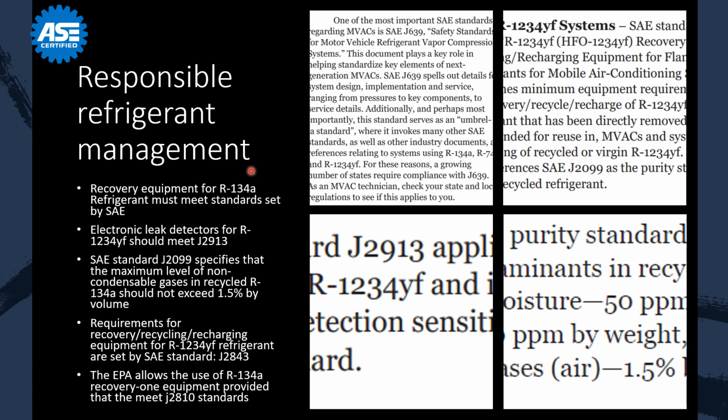R134A, the equipment for R134A has to meet the standards that are set by SAE. There's a standard for the electronic leak detectors on R1234YF. There's going to be standards for the maximum levels of non-condensable gases in a recycling R134A should not exceed 1% or 1.5% of the volume. There's going to be a standard for the requirements of recovery, recycling, and recharging this type of refrigerant. So there's going to be a different standard for R134A than there is going to be for R1234YF.